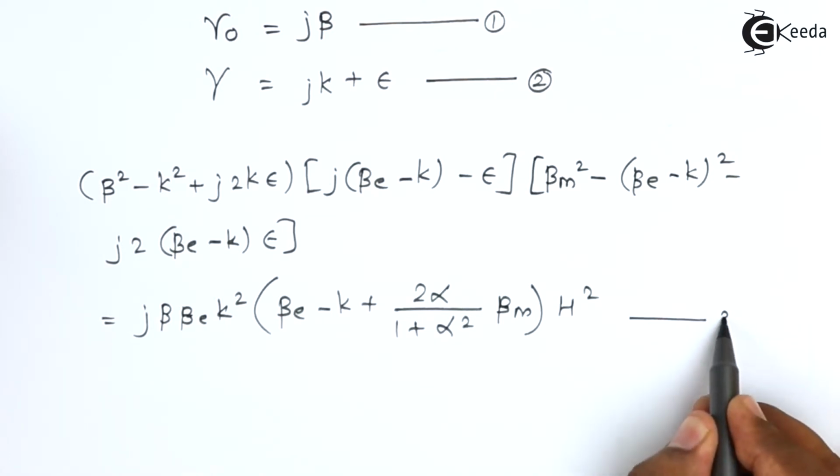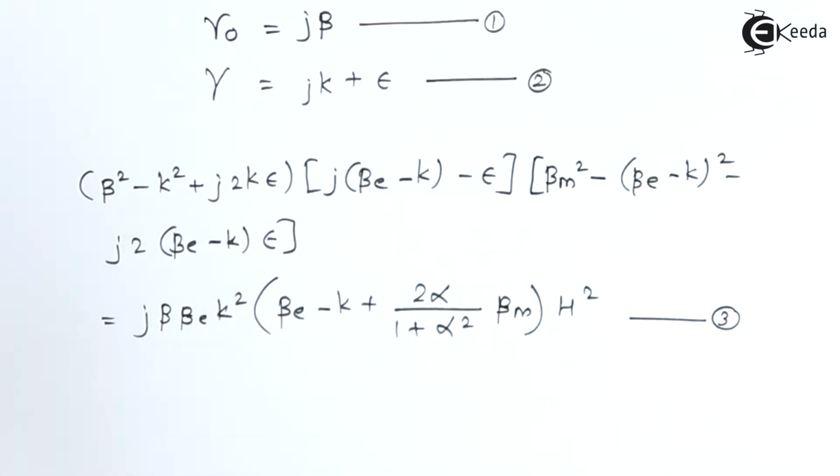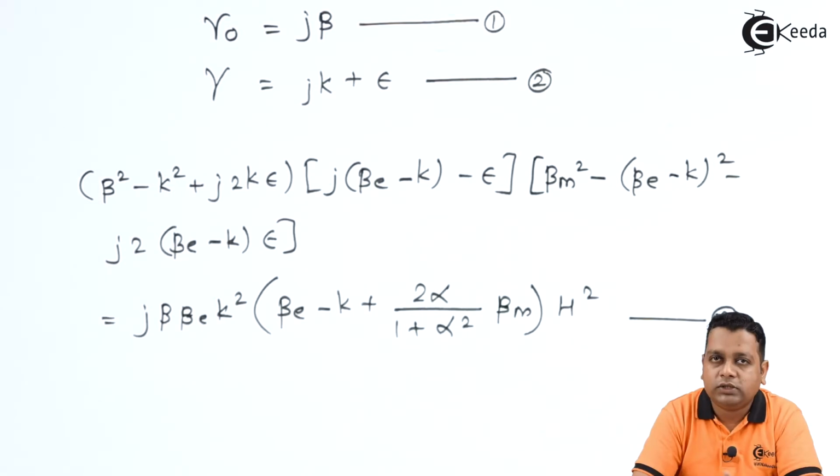So this is the representation of equation number 3. In this equation, as far as the propagation is concerned, alpha accounts for the attenuation, a kind of loss in the propagation. Beta represents the change in the phase during propagation, which is very necessary. So beta represents the phase shift constant, and gamma, which we have in equations 1 and 2, is the propagation constant here.